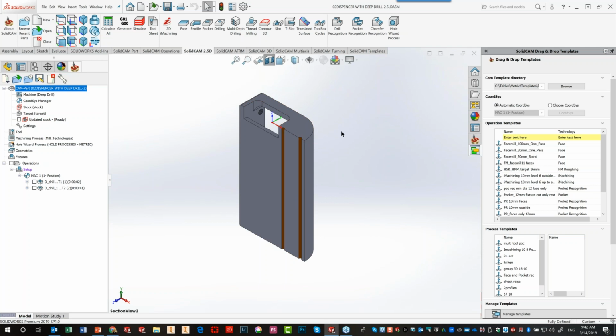So we have to have a long drill to actually drill all the way down to the bottom, but we want to have full control of our drill. Now, normally the way we start, I've just done it in this particular way. I already created a spot drill for the first operation, a regular drill to go down as deep as I can with a regular drill.